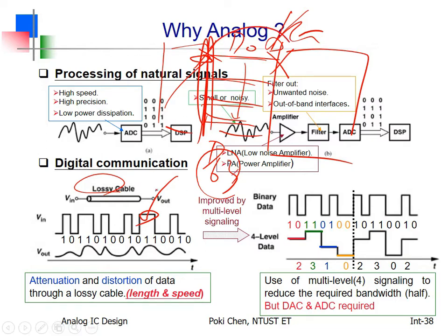That is one major issue why nowadays almost nothing is parallel for high-speed communication. Everything is in serial. But why? The secret is we need to embed the clock into the data. So never mind what kind of skew, what kind of jitter.